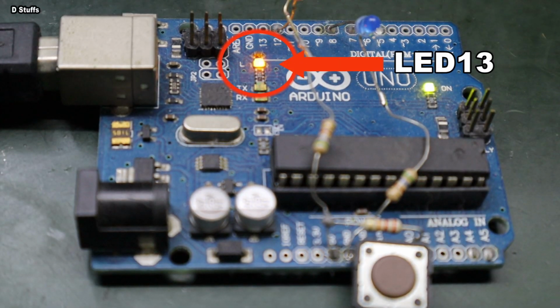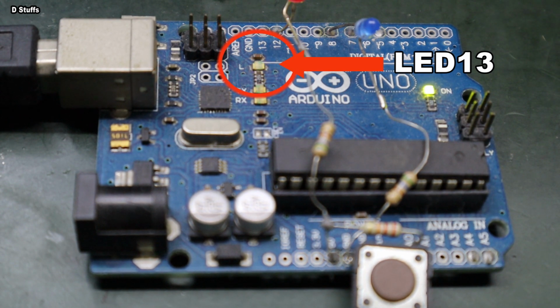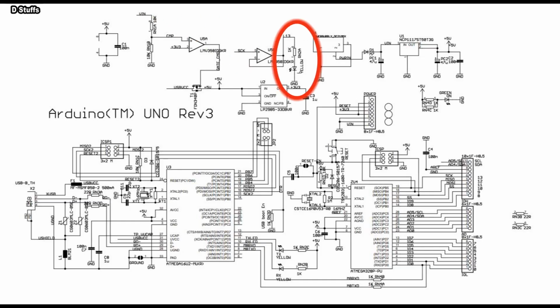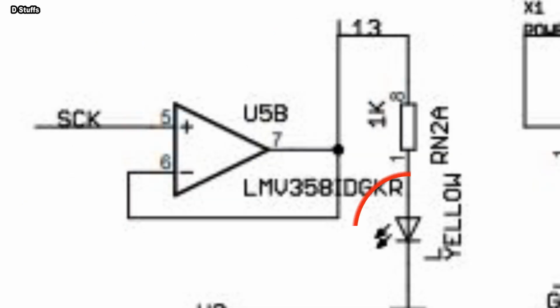The popular LED 13 on the Arduino Uno board was connected to digital pin 13. It was interfaced as a current source configuration where it needs to send a logic 1 to light the LED and send a logic 0 to turn off the light of the LED.